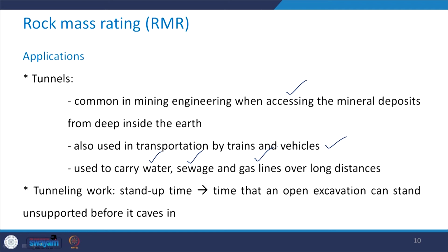So, once you have made the excavation, one needs to go and provide the support system. That support system can be in the form of lining, shotcrete or rock bolts. So, the stand up time defines the time that the excavation can withstand unsupported without caving in.